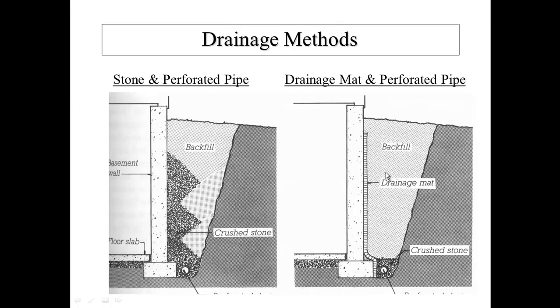One of the problems we have with foundations is if you've got a roof overhang up here and water constantly drips off the roof, it's going to cause a washout or some type of erosion along the side, which would allow water to sit in this valley for longer periods of time and actually get into the foundation. So keeping the slope away from your building, so that water falling off the roof drains away quickly rather than getting down into the foundation, is another good method, and sometimes this requires some maintenance.